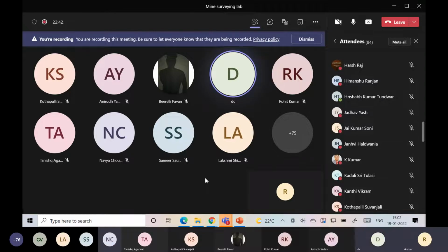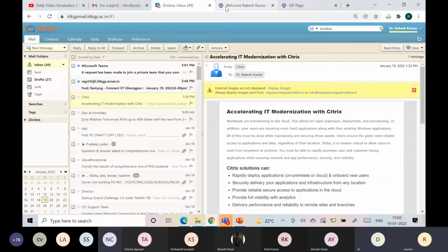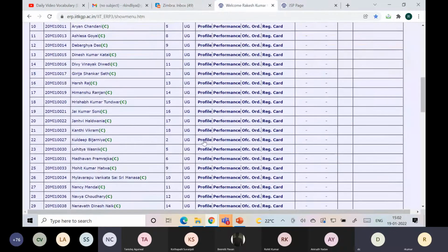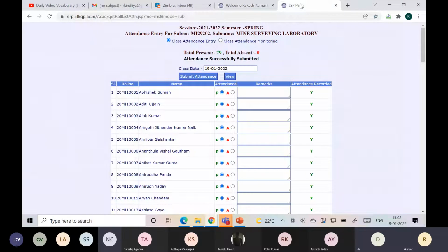In surveying we have, as I was telling, trough compass, surveyor's compass, and prismatic compass. These are the three main categories. The trough compass, which you have seen in the demonstration for the first lab, is mainly used with the plane table. Surveyor's compass and prismatic compass are what we use in the field, and in today's experiment we will go for them. Your screen is shared, Rakesh ji?